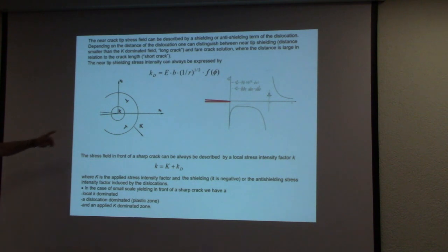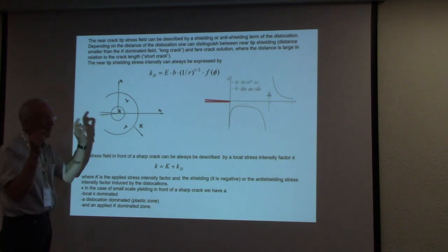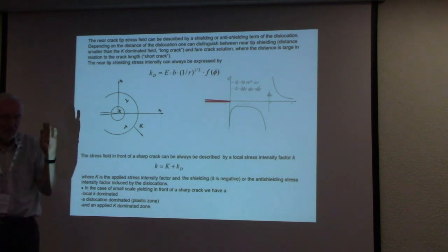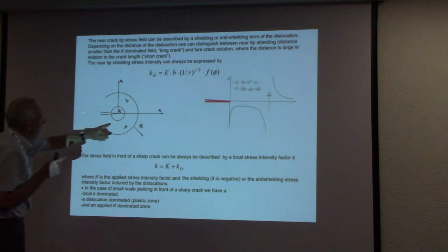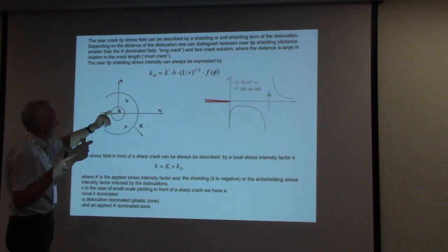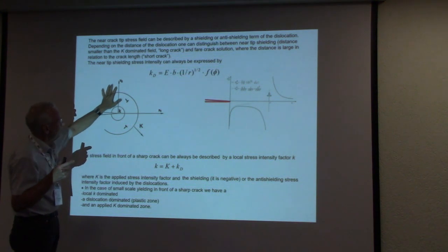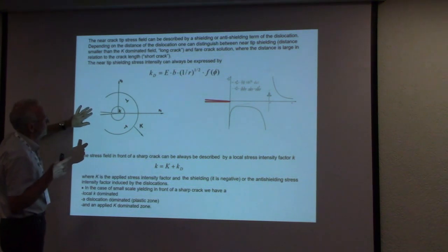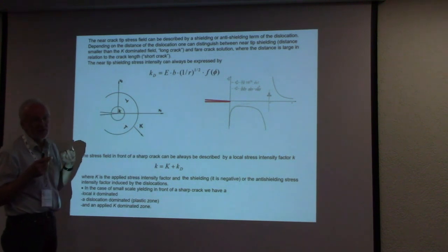And it is interesting that you can really describe by a linear elastic description the stress at the crack tip, and the stress at the crack tip is simply given by the applied stress and the stresses induced from the dislocations.